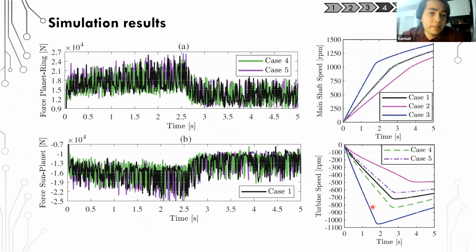Besides the main shaft inertia, another major component of this analyzed machine is the superimposing shaft element, and it was also analyzed. But as we can see, unlike the main shaft element, the variation in the superimposing shaft inertia did not represent an expressive change in the meshing teeth contact.